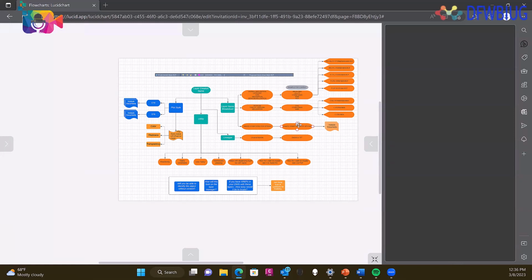No, I mean, you make good points about layers. Every company does a little bit of something different. As a consultant myself, I do templates and I would say everybody's is slightly different. I'm more on the private sector, not the public sector, so I can't speak for the public sector, but the private sector kind of does their own thing. They'll tweak it, they'll spell out words. Sometimes they'll do initials. But one thing I always recommend is don't go crazy with the layers.